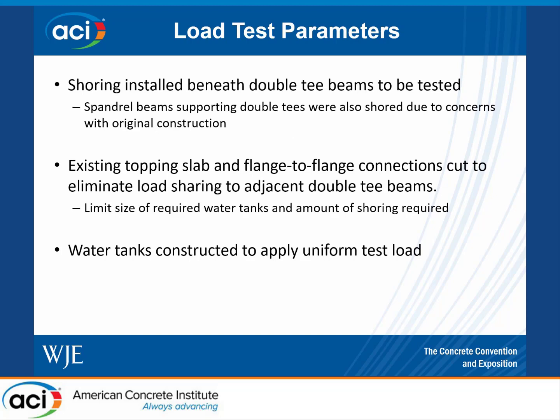Shoring was installed, as I discussed, below the double T-beams. And we also installed shoring below the spandrel beams that supported the double T's to be tested. There were some concerns, given the cracking that was observed in the double T, that we could have similar issues with the spandrel beams. So to be cautious, we shored the spandrels also.